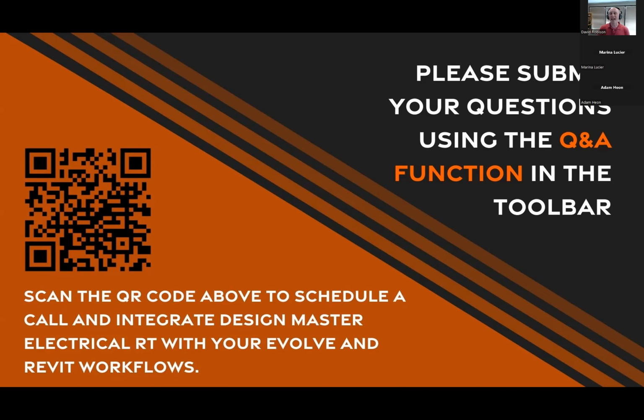These are definitely engineering lengths and not contractor lengths. So don't cut wire, please, based upon these values. But for the engineering side, for fault and for voltage drop, they're good enough that they're going to give you correct answers with as many other assumptions as there are in those calculations. And then eventually, we would like to be able to pull the values back from Evolve so that these are being filled in with the actual conduit routes that you trace.